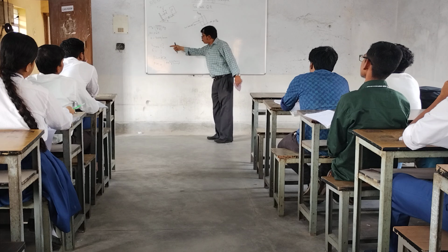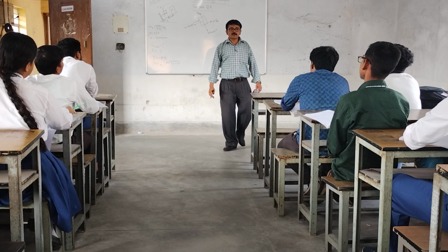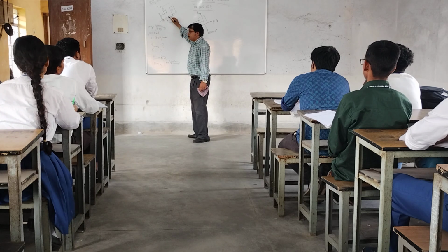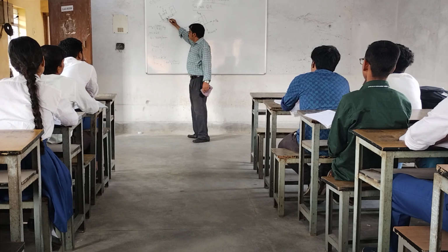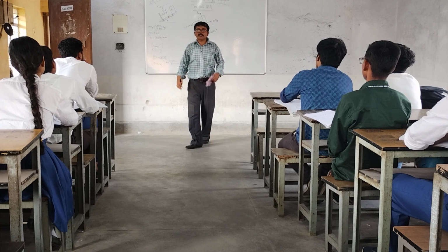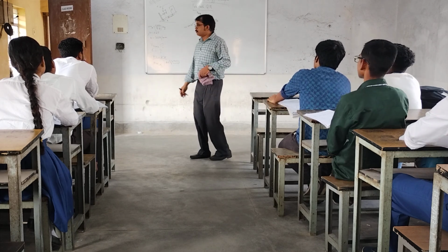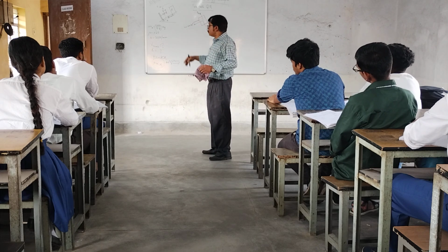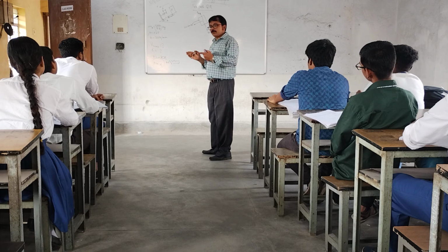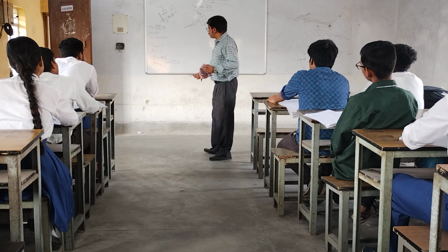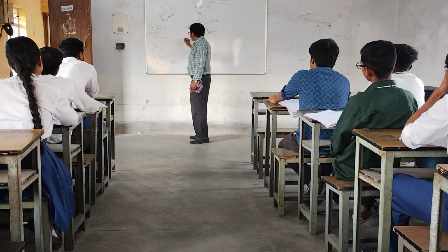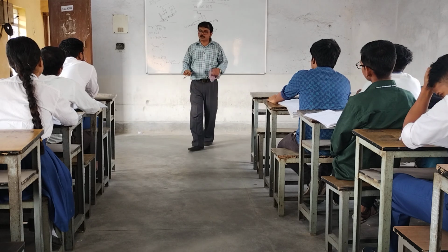The vector is in this direction, so we have considered the sign. You can see the spring force varies from 0 to k delta. Now how much work is done? The displacement is delta, and the force varies linearly from 0 to k delta. In the formula, work done by the spring force is force into displacement.